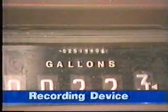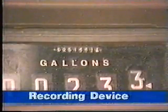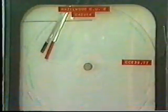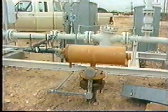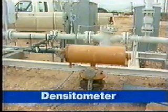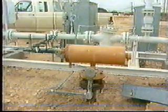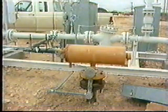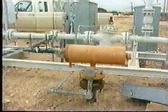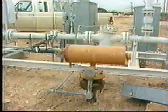A recording device is found on all meter runs. This device records volumes digitally and on charts for sales and purchase records. A densitometer records the density or mass per unit volume. The gravitometer records the liquid-specific gravity, which later can be converted to density using the density of water at specified conditions. Most NGL runs will have a densitometer or gravitometer.